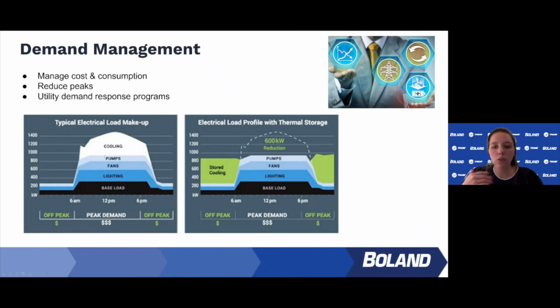Thermal storage helps you reduce this demand peak during the day, and it transfers the energy use overnight. So demand is flat during the day and consumption increases overnight, and you use that cooling to help condition your building the next day.